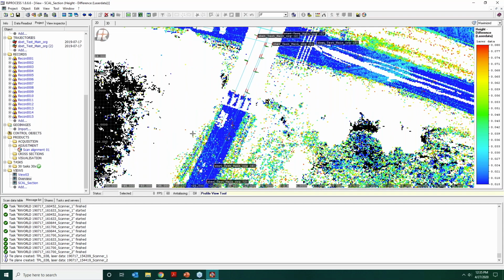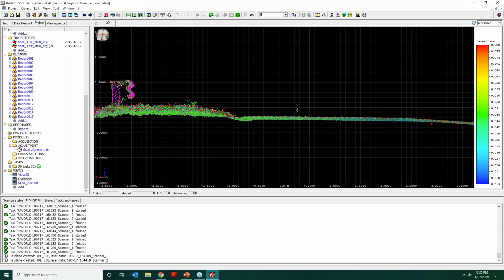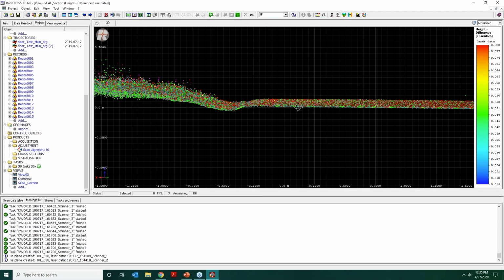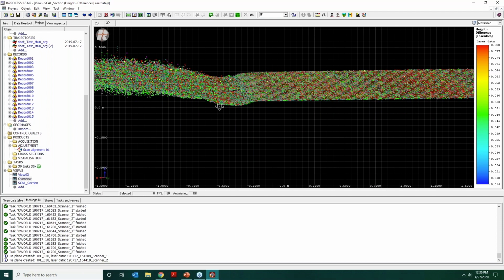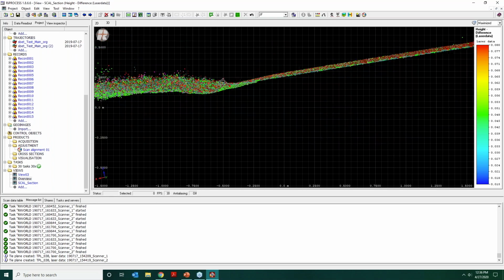And you can check that also in here in the area after the bridge, before we had our final cross section placed. How does that look? It looks pretty good as well. At least it's saying that it does. Let's just make sure it's not lying to us. It appears to not be. The road didn't shift sideways where you get that little offset in the side gutter there. The color differentiations you're seeing are from the slightly different angles of two different passes, getting into the gravel area or the soft area.